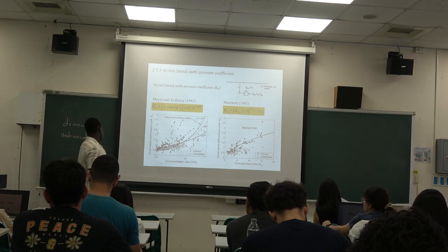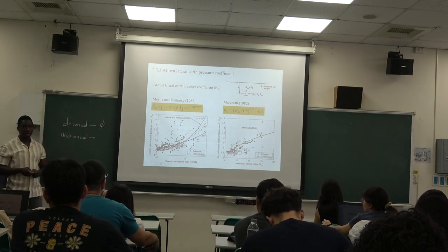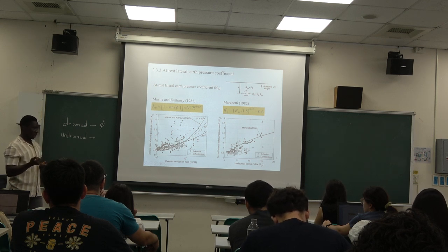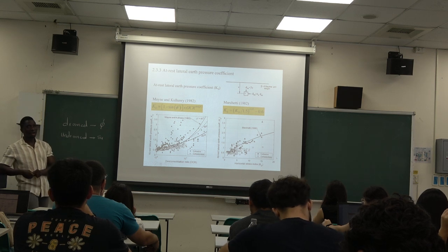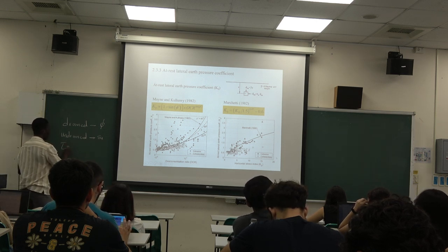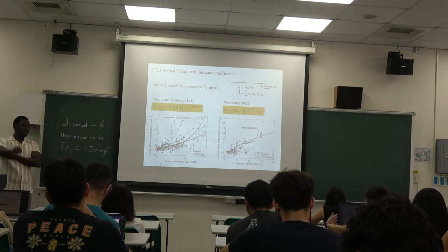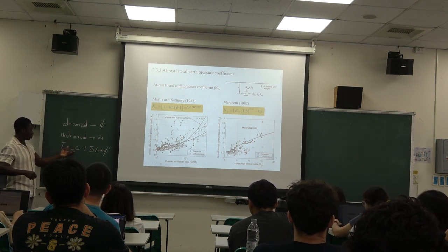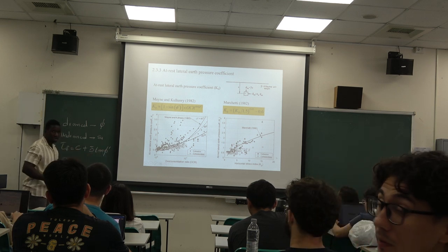And we also talked about if it is drained, for example, coarse grain soils, then the strength is controlled by the friction angle, that is the internal friction between the particles. But if it is undrained, for example, clay and silt, then the strength is dependent on the undrained shear strength, that is the Su parameter, okay? And we also gave a brief introduction about the Mohr-Coulomb failure criteria. We say the shear strength is c plus sigma tan phi, right? So if it is undrained, the shear strength is controlled by c, because c will be Su, right? But if it is drained, then c is mostly 0, so it is controlled by the friction angle.